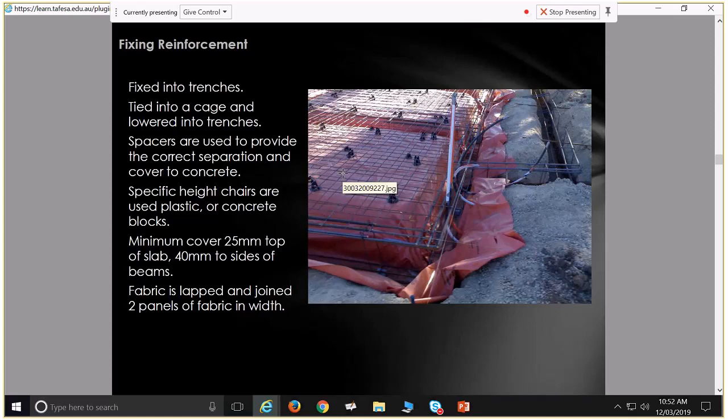Also, I guess the slab's a lot thicker than when I was brick paving. The method that I was using is a bit different to most. We used quarry rubble and sand, and whacked it to a point where it was like cement, before you put the pavers down. By using quarry rubble and quarry sand, we found that after they were laid, at least for a little while, maybe one or two times, salt damp would come up through those particular materials through the pavers. A very strong way to lay them, but you'd have to clean the salt damp off a couple of times, and after that it would not happen again.